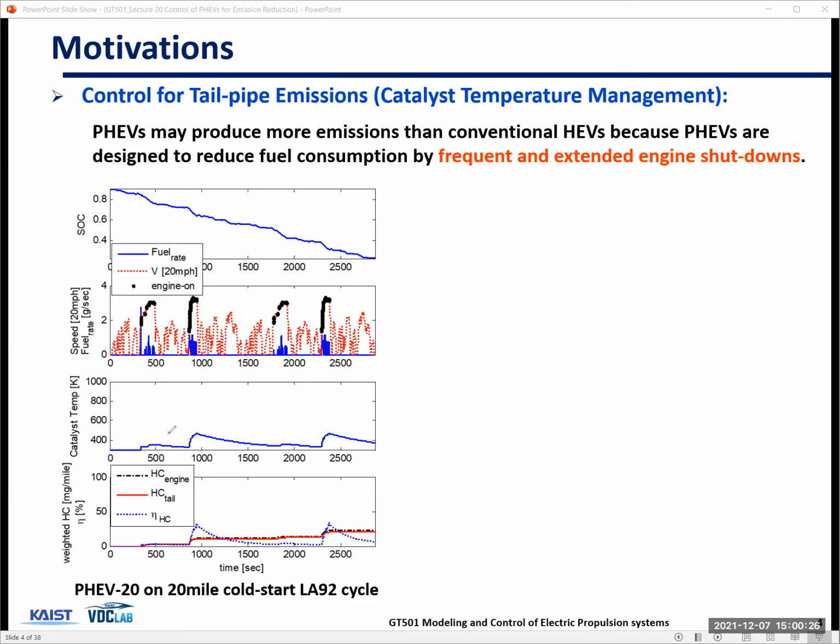And because of that short time, the catalytic converter is rarely activated. Okay, I think the activation temperature is something like 500 K. So that means the aftertreatment system is never activated.